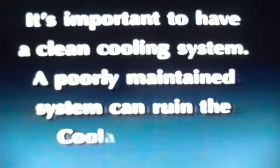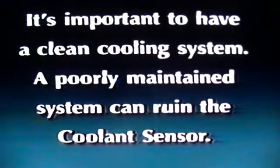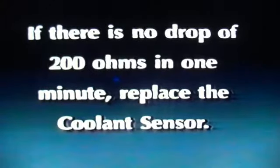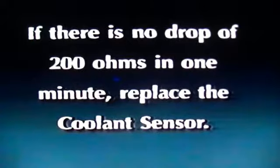Incidentally, the threat of dirt and deposits is why it's so important to have a clean cooling system on today's cars. A poorly maintained cooling system can ruin the coolant sensor. If cleaning the sensor doesn't result in a drop of 200 ohms in 1 minute, it means you'll probably need a new coolant sensor. The next 4 checks must be done while the engine is still cool, or you won't get the answers you're looking for. Answers that can solve a lot of cold drivability problems.